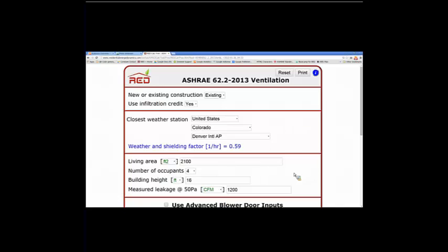And the response to that interpretation request, this was about 2 years ago, exactly the same question. This has to do with the 5 air changes per hour for the kitchen. It's either 100 CFM on demand or 5 air changes per hour running continuously.